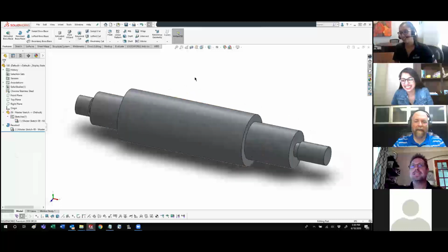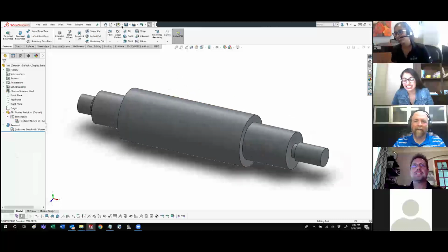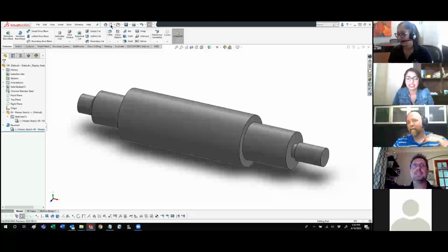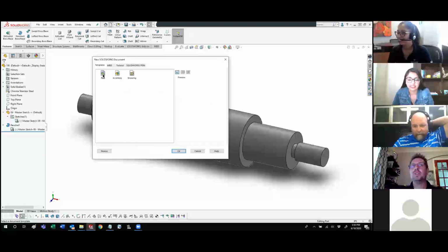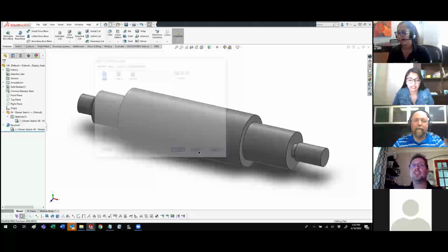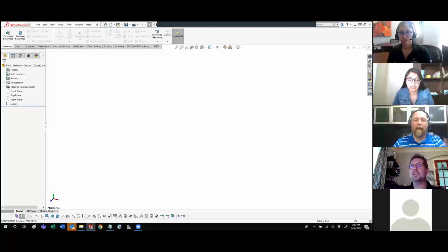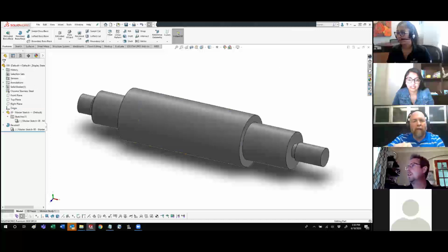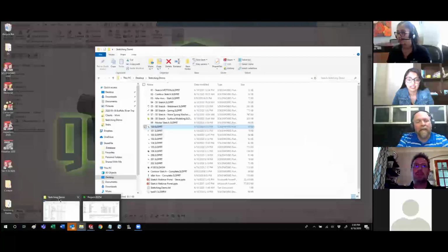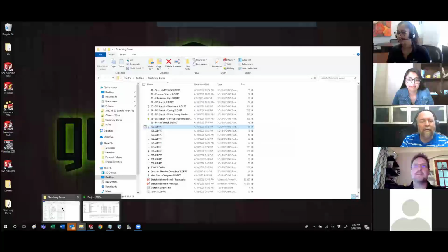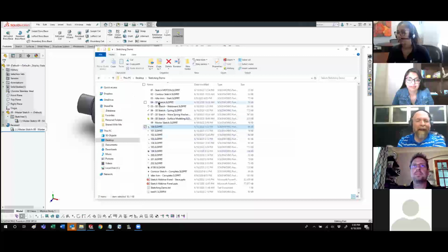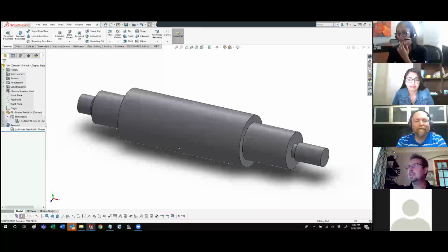He says really the only way is to draw a construction circle and make it tangent to the 3D spline. Now, the other thing you can do is view the 3D spline, so you can turn on what the minimum radius is. If you know what the minimum radius is, you can see what the actual radius is. But actually controlling that with a dimension, because if you attach part of it to that circle, the next part of the spline might violate the minimum. So then you're spending all day chasing that too.